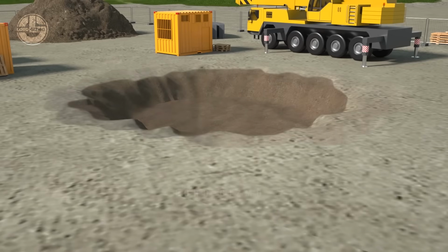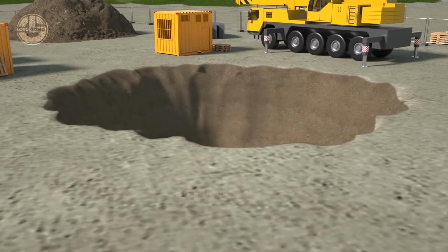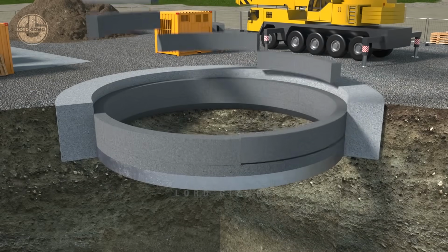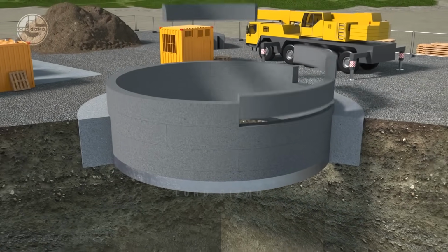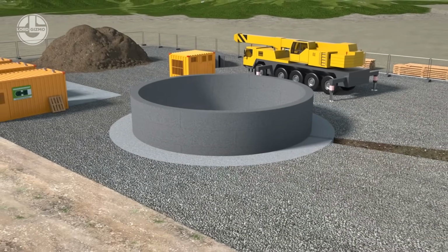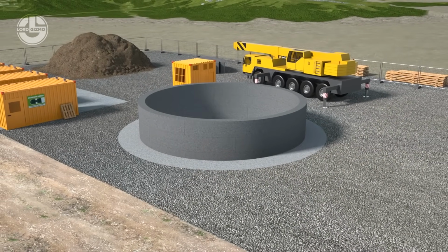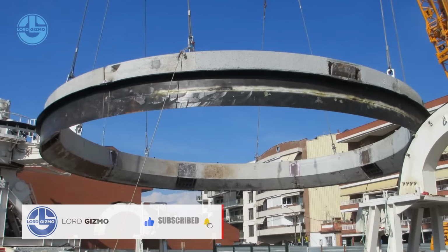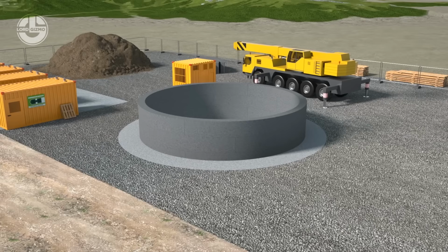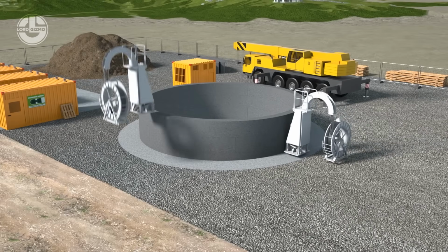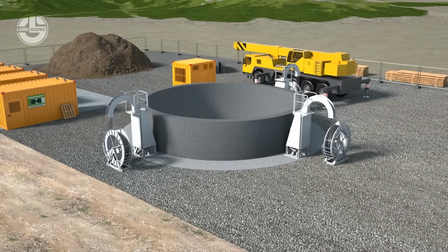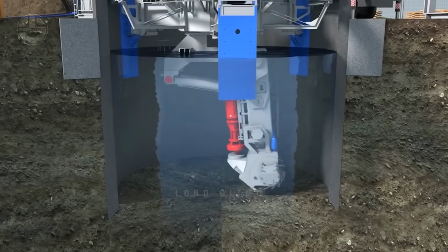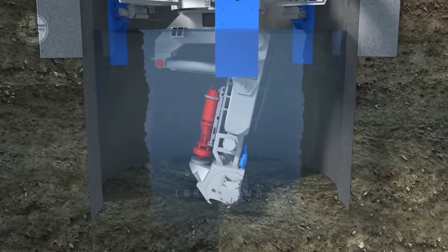First, there will be a 1 to 2 meter deep excavation where the initial section of the shaft is. Then, a support concrete ring beam is installed. The purpose of this is to absorb forces from the shaft sinking process. The lower segment ring of the shaft, which has an integrated steel edge that functions as a cutting knife, is assembled and raised first. The number of strands that connect stranded jacks and strand wires to pockets in the cutting edge is equal to the entire weight of the shaft.